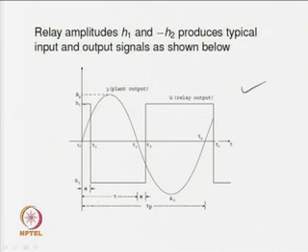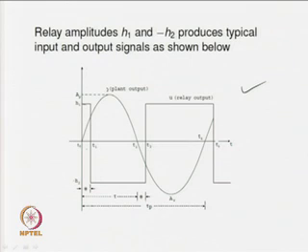For the time T 1 to T 3 we are getting negative input to the system with a different relay height. From time T 3 to T 4 and beyond, the input provided by the relay is again piecewise constant with the same amplitude, positive H 1. So, when one considers one period of the output signal, spanning from time T 0 to time T 4, we have got 3 piecewise constant inputs to the system.